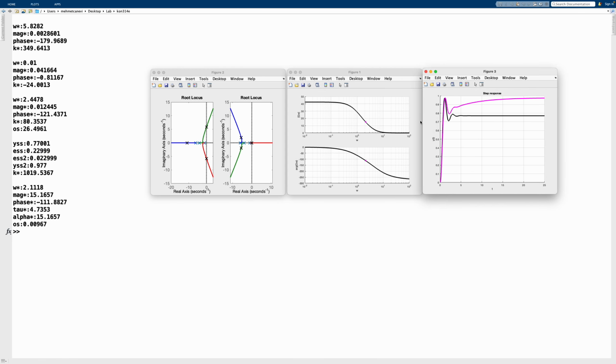There we go. Now we see that in terms of the transients up to 5 seconds, it seems like it is the same in terms of shape, but we can see that there's a slow mode, and that's probably the lag controller here. It takes slowly action, and it forces the system to reduce its steady state error tenfold.